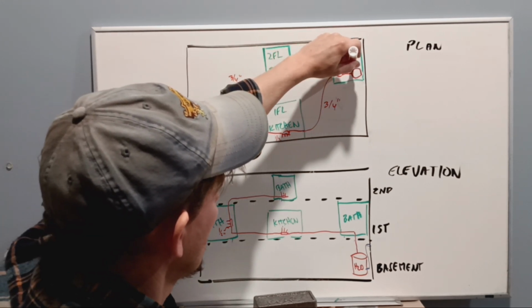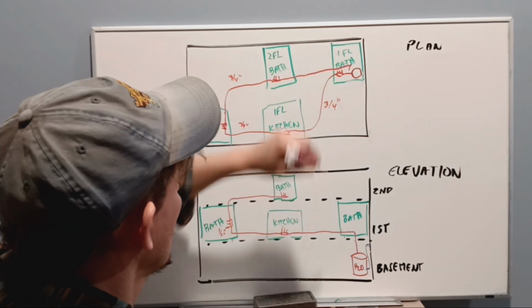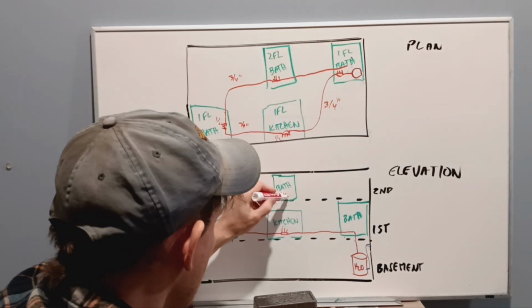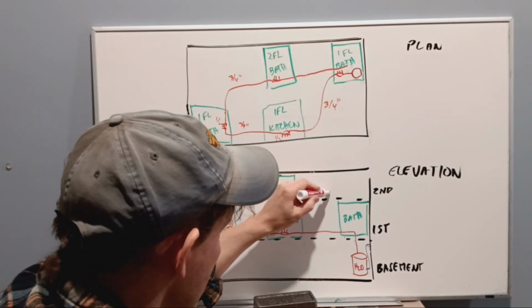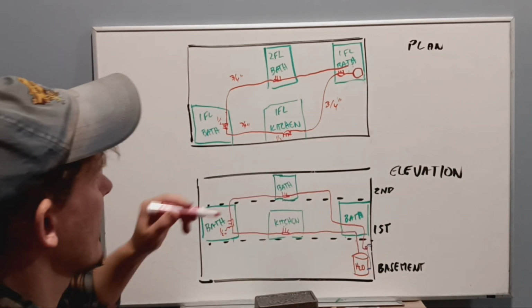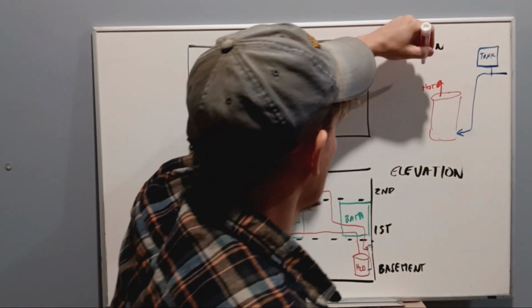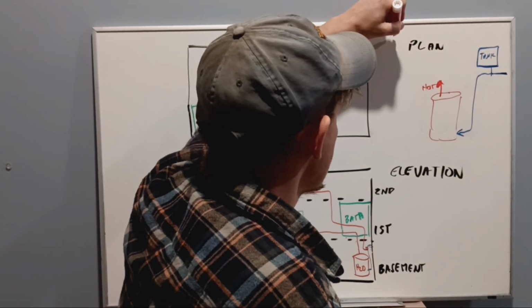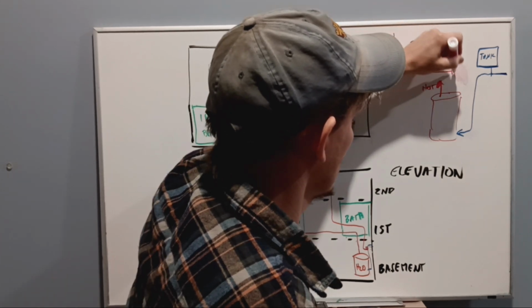Okay, this is a super important detail here regarding the difference between an active and a passive system. In the active system, a circulation pump is put in the return line that forces water towards the tank, reheating it and sending it back through the hot water loop. This pump also prevents cold water from circulating around the loop backwards.